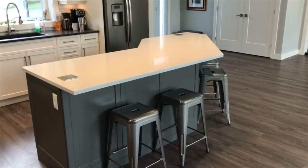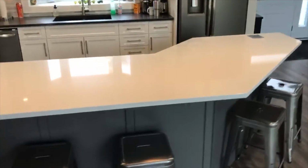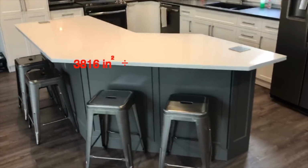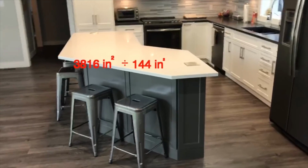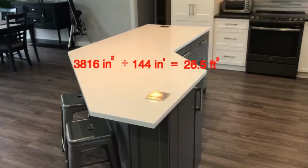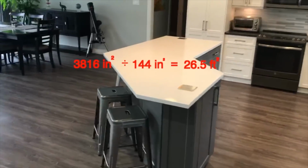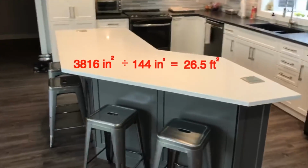Now we can go back to the total area of the countertop in square inches and convert that to square feet. If we divide the 3,816 square inches by 144 square inches per square foot, we find out that the countertop has an area of 26.5 square feet. Now the builder can check the supplier's cost per square foot for the quartz material and find out how much the countertop will cost.